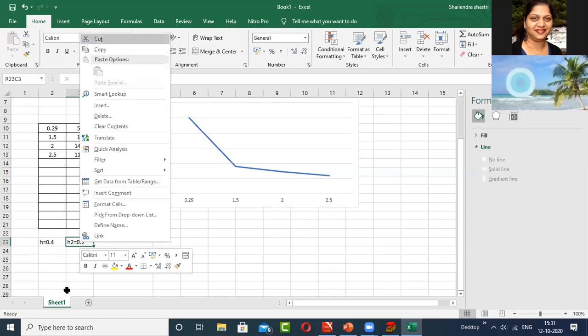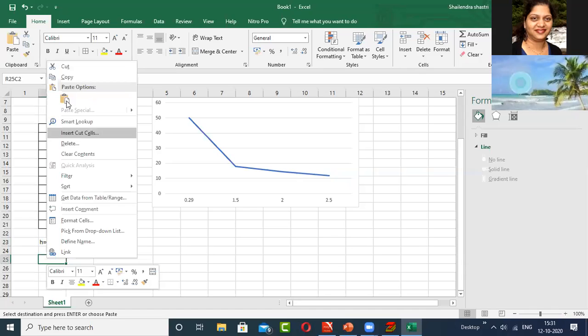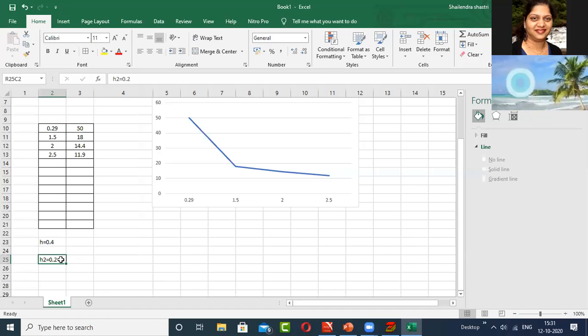Sorry, this time it is a variable, so I will keep it here. We are going to analyze the behavior if the line is asymmetric in nature. Width I will keep fixed, suppose 0.29 mm because it's a 50 ohm line, if H1 and H2 both are 0.4 mm.